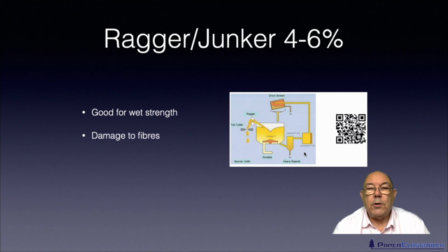Amongst the contamination, other than plastic, you might find coins, nuts, bolts, lumps of metal, glass. Glass will be shredded, of course, but heavy pieces of metal will fall down here into this device that we call a junker. And typically, either once a day or once a shift, someone will open a little door in here and pull out all that metal and close it and carry on.